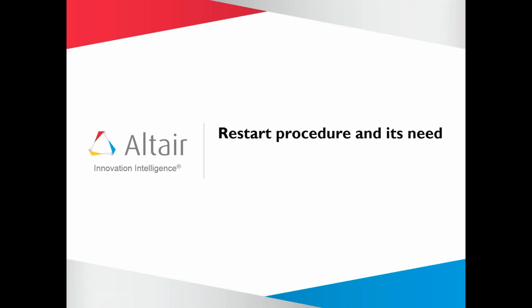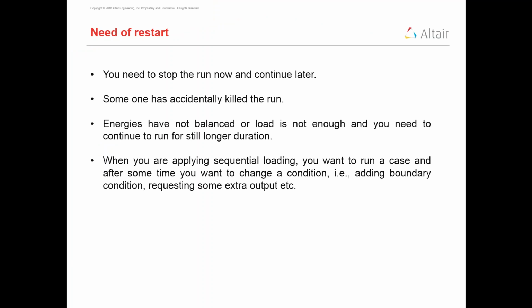The topic of this session is the restart procedure and its need in RADIOSS. So what is the need of restart? Suppose you need to stop the run and continue later, or someone has accidentally killed the run, or the energies have not yet balanced, or the load is not enough and you need to run for a still longer duration. Then you have to go for this restart procedure.